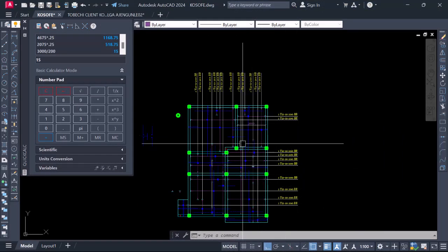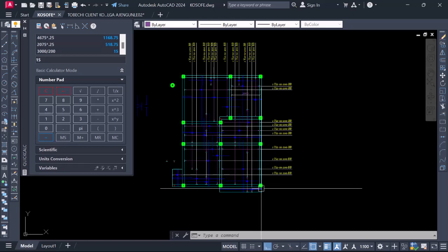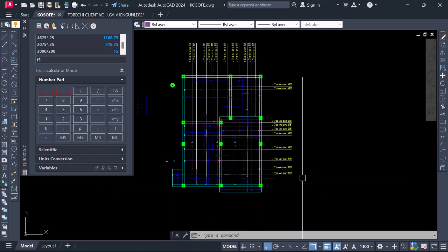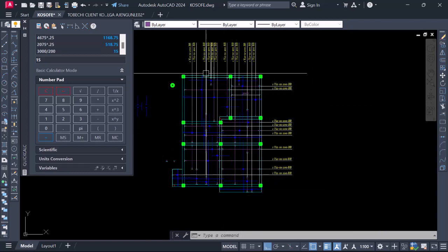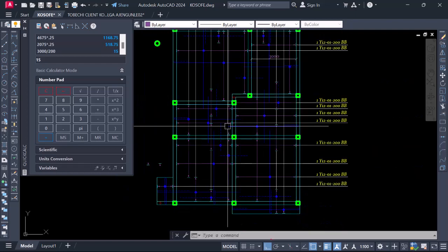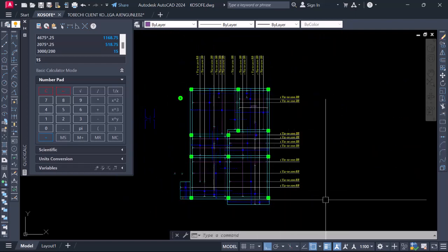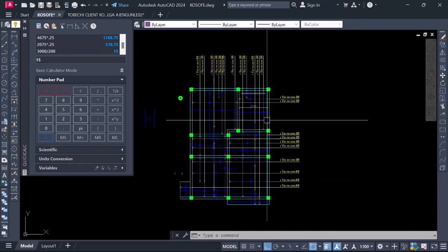This is what you need to know while you're detailing. To simply identify this, all the horizontal direction you have to detail on this other side, and all the vertical, try to place on the other side, unless you have limited space and all the rebars are clustering, then you have to create it on this other layer. But always try to put the detail running across the span, like this one.